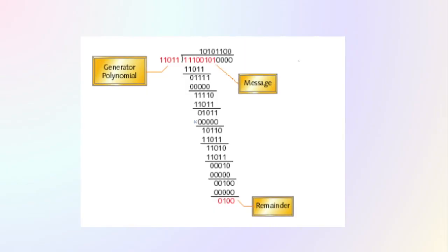Now, just a basic premise of CRC, you will see this everywhere: CRC itself is just a division algorithm. CRC is a remainder, right? We all know that CRC is just a remainder, where the message is the number being divided, and the divisor is your polynomial. This is really all there is to it.